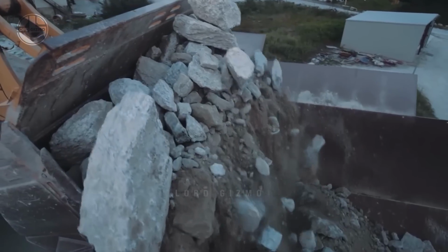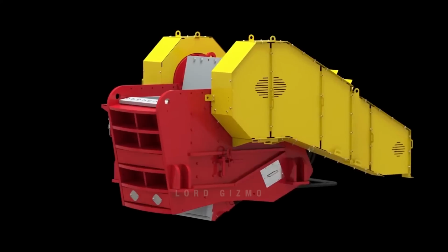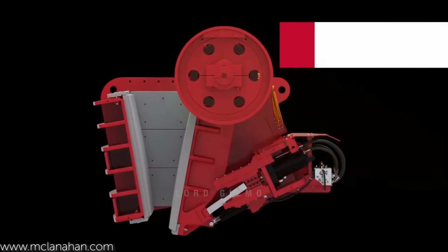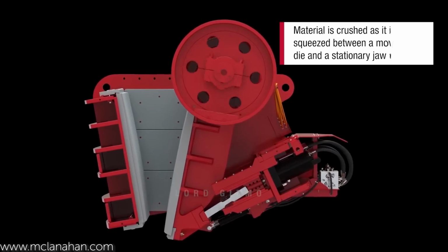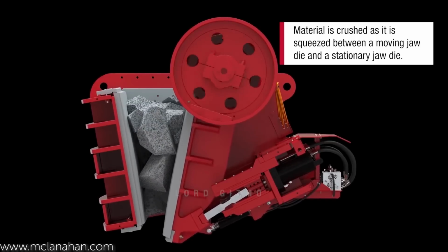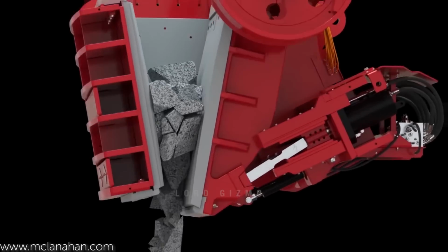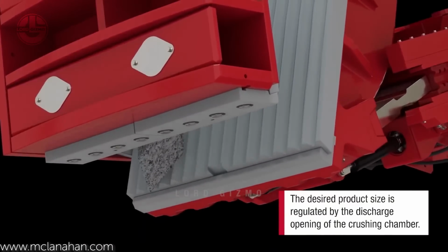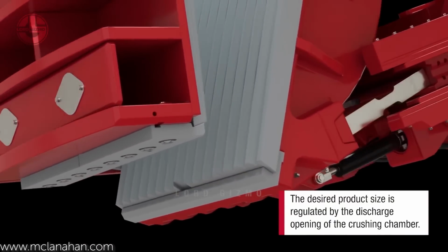There, the sandstone goes through various crushers to achieve the desired particle size distribution. This is the McClanahan jaw crusher, which acts as a primary crusher for sandstone. It consists of two opposing jaw dies that create a V-cavity called the crusher chamber. The material is squeezed between the moving jaw die and a stationary jaw die. The discharge opening controls the desired product or yield. Typically, the mined ore is reduced by a jaw crusher to about 1 inch in size.